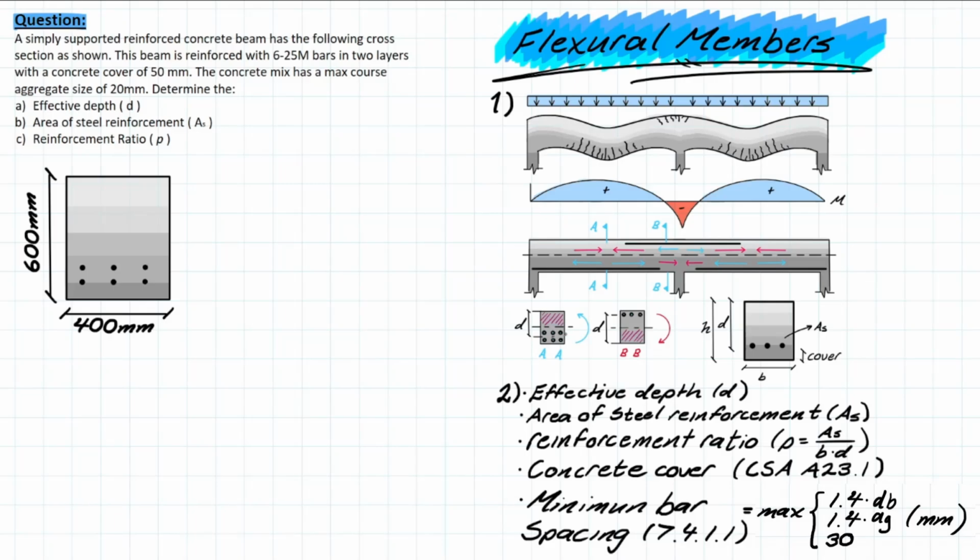So you see in this picture over here, I have a reinforced beam or member that has two layers of reinforcement. And the reason why that is because reinforcement may be designed to a certain quantity and they will be touching each other if they're all in the same layer. And that's no good for concrete because concrete needs to get in between these tiny cracks that are between the reinforcement. And in order to do that, it needs space. And if you can't squeeze them all into one layer, then you're going to add another layer. You're simply going to move up a level in order to place that additional reinforcement. Now, in order to design this minimum bar spacing, we have to look at A23.3.